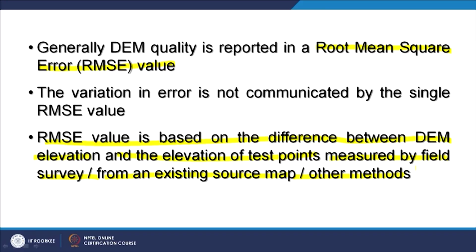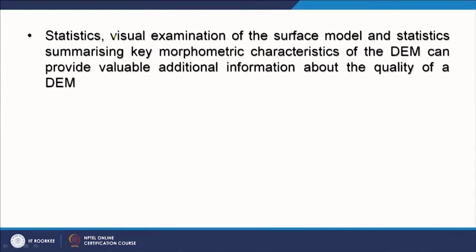If I have that data, generally when you start trying to assess the quality of a digital elevation model, I am sure that one way or another you may get some test points, some true values for your area, which you can employ to assess the quality of a DEM. RMSE or any other analysis which you would do are basically statistical analyses. There is also, for example, visual examination of the surface model, because if the surface model or DEM is suffering from voids, then you can assess that visually. If it has seams, you can assess that very easily visually.